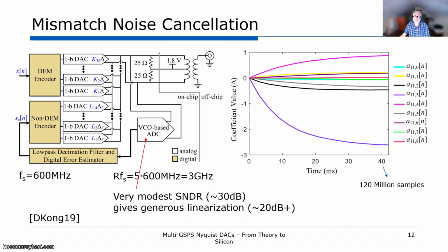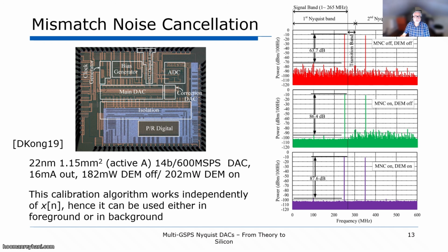And we will evaluate their effectiveness and associated trade-offs, complexity and cost, and in terms of power consumption, area, design time, etc., etc. And again, we will put the suitability of different approaches into the application context. For instance, some of the calibrations are best run when the DAC is powered up and before it is used to perform its conversion job. But parametric shift happening during normal operation won't be corrected.